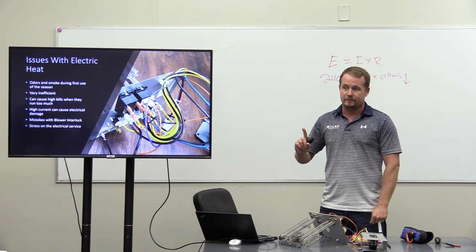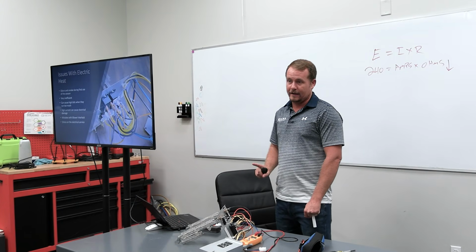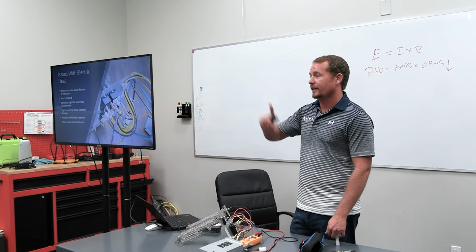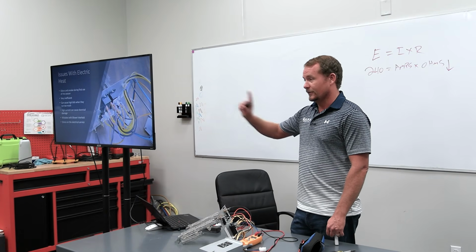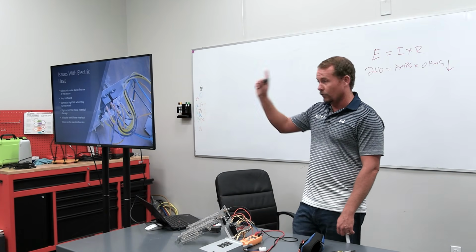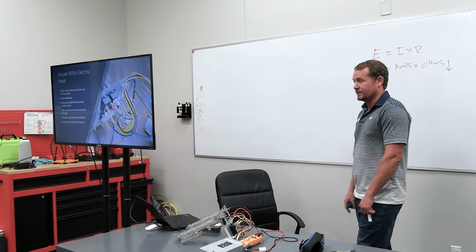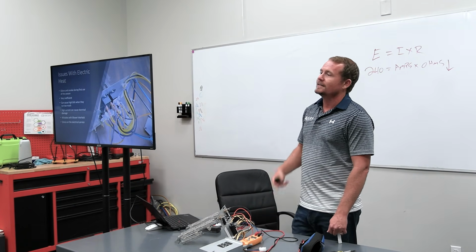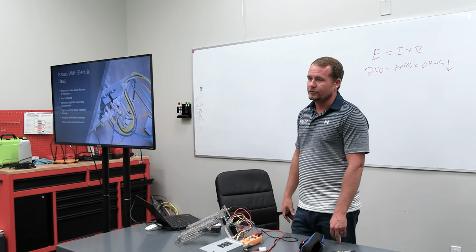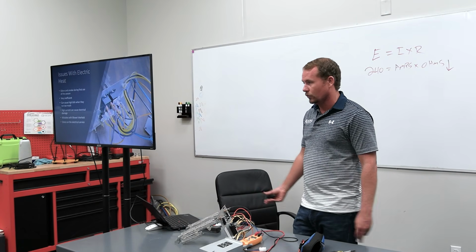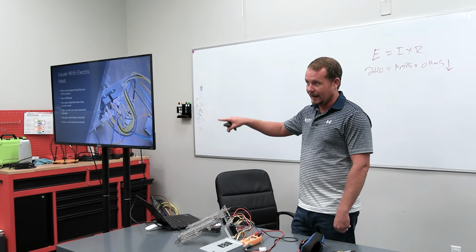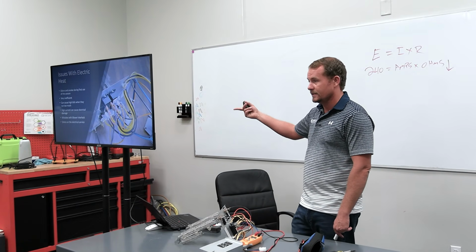Ask the question. Look at what else is in that home and see, is it going to be potentially a problem? Because let's say they already converted a gas dryer to an electric dryer. Okay, well, they're right there. You've already kind of screwed up, and now you're just going to keep adding electrical appliances to it. In many cases, it's not a huge deal to upgrade a service. It's not like the end of the world. Maybe $4,000 or $5,000, something like that. But if that has to be done, it has to be done before we put our system in.